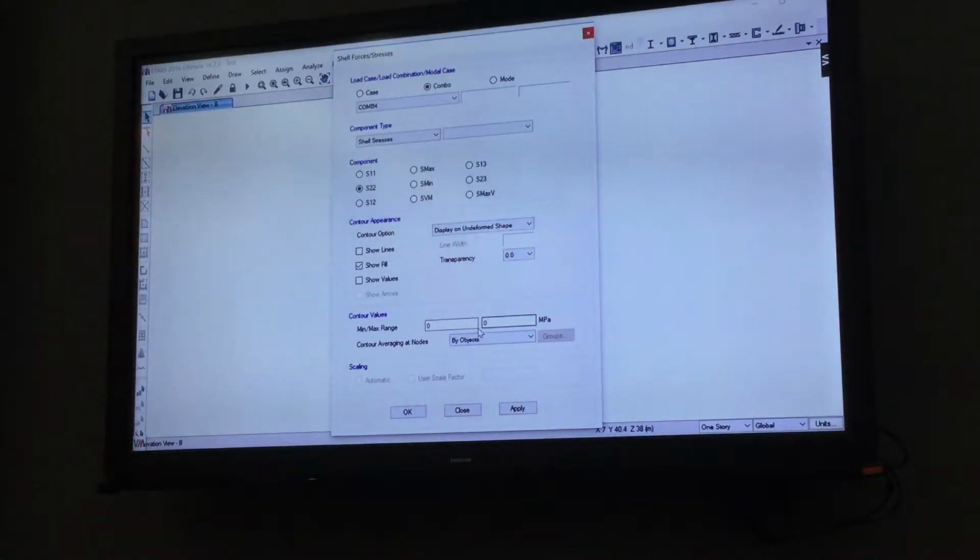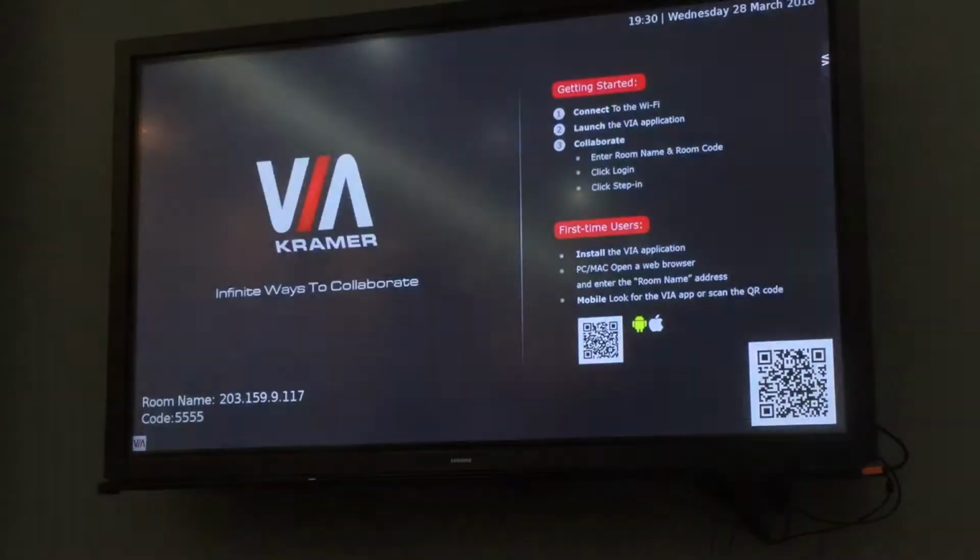And by objects, for example, in this shear wall, we use a concrete compressive strength of, let's say, 41.4 megapascal. So if we go to 0.15 f'c, it will be 41.4 times 0.15, about 6.2 megapascal is the limit.